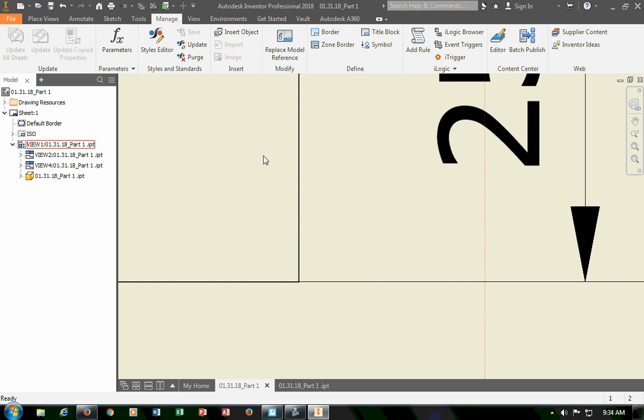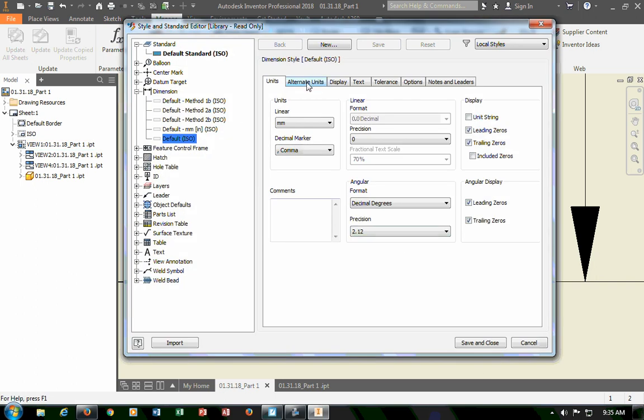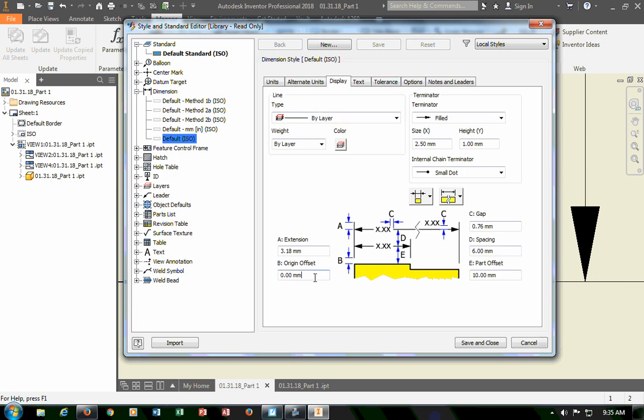Yeah, it's right on it. Do we like our dimensions to be right on our parts? No. So you're going to instead have a gap of at least 1/8 of an inch. Now, 1/8 of an inch is what in metric land? 0.125 multiplied by, what was that number? I forgot. 25.4. So 3.175, which, by the way, is what this dimension is.